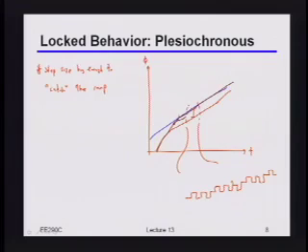Now, of course, there's still going to be the dither around there. But at least the size of that dither is not set directly by the frequency error that you're tracking. You still have to make sure that you can keep up with that ramp. But the good news is that since we're only going after a few ppm, that's usually a pretty easy thing to do. Okay?